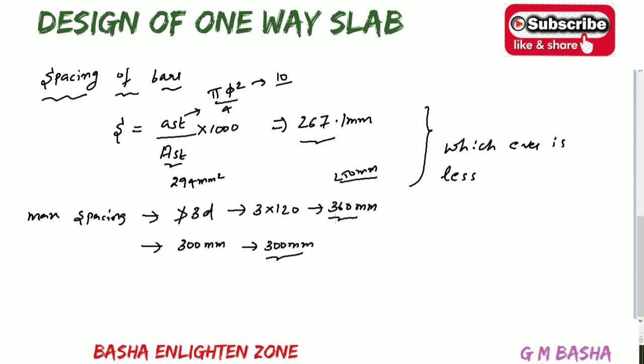But sometimes, based on the effective depth, it will be 250 mm, and even if the other two values are higher, you limit the spacing to 250 mm, because whichever is lesser governs. That is how you have to consider the conditions.